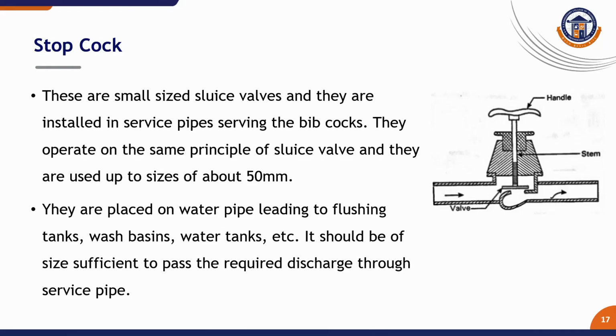And next, the stopcocks are small sized sluice valves used in service connections, especially upstream of bibcocks or flush tanks. The typical size of the stopcock is up to 50 mm. It allows control of water flow into individual fixtures like wash basins, toilet, or overhead tanks.